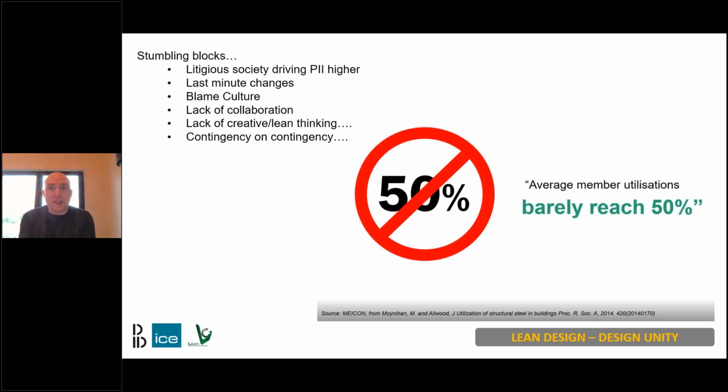And don't forget that the design capacity of an element, if you're following the design codes, already has factors of safety in there, and those factors of safety are there to cover things such as lack of fit or slight tolerances on site, and maybe very local increases in design loads as well. So you're already including a 50 to 60% increase in the design loads or decrease in capacity when you're looking at the actual design of a member.